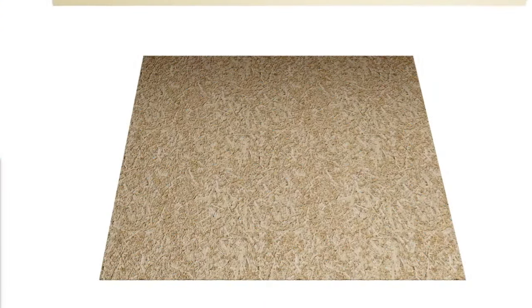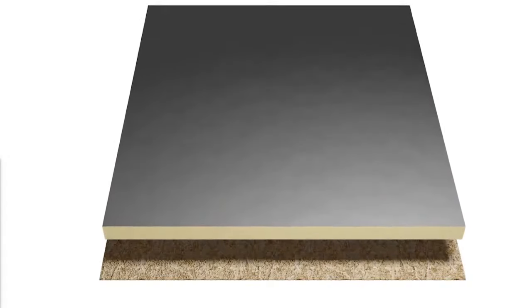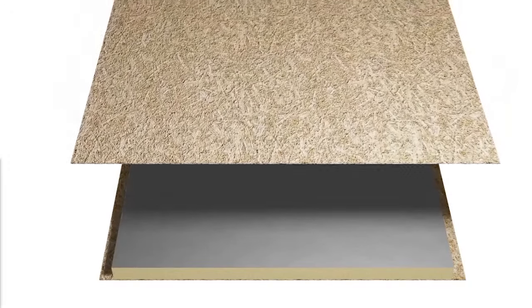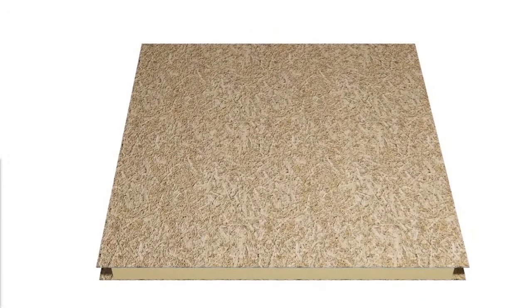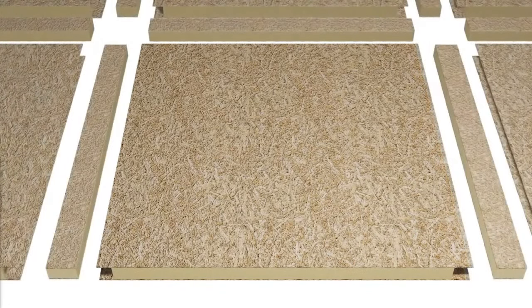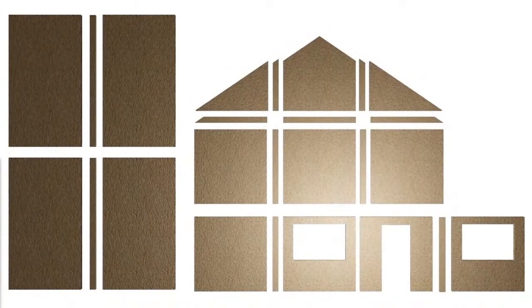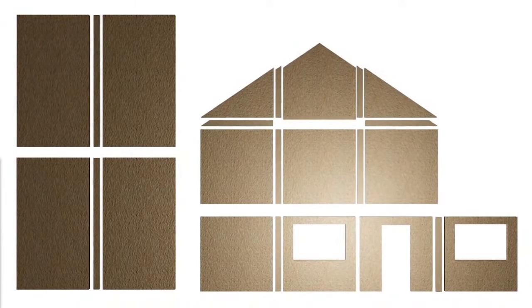The last of the most common methods of house building is a structural insulated panel, which is the type of construction my house used. A typical insulated panel comprises timber sheets, usually OSB, sandwiching a core of rigid foam insulation. Because these panels are not bridged by any less insulating structural materials such as studwork, they can match or exceed the thermal performance of a traditional timber frame wall with substantially less thickness.